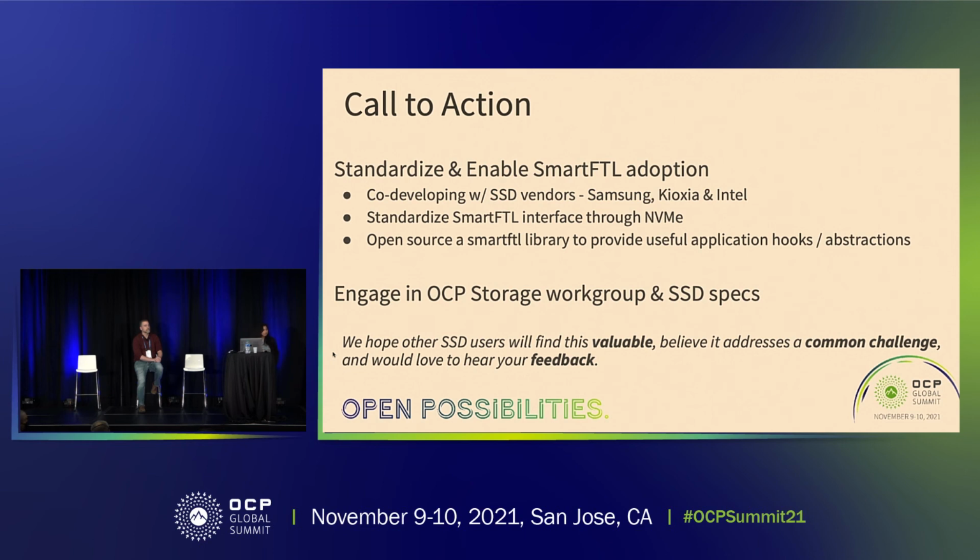I have a question. There's an architecture called Open SSD, where the host manages a lot of the functions. Is this something similar to that? Is this like Open Channel? Open Channel, yeah. So I think Open Channel is something we looked at along the way in the development of this, and we saw a lot of limitations imposed by that on the drive in terms of NAND management, or cases that were not optimal.